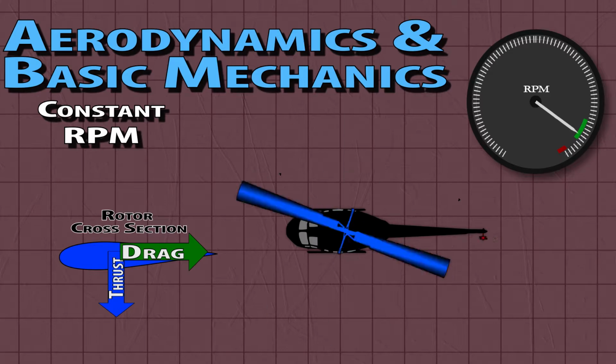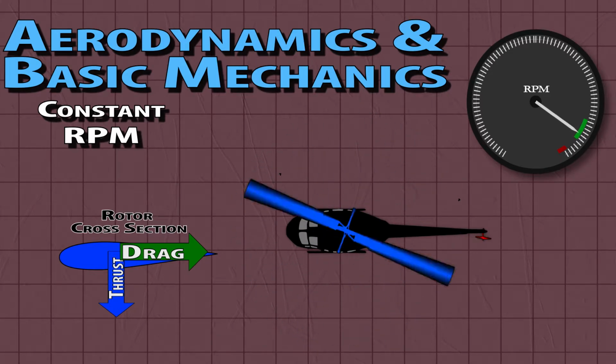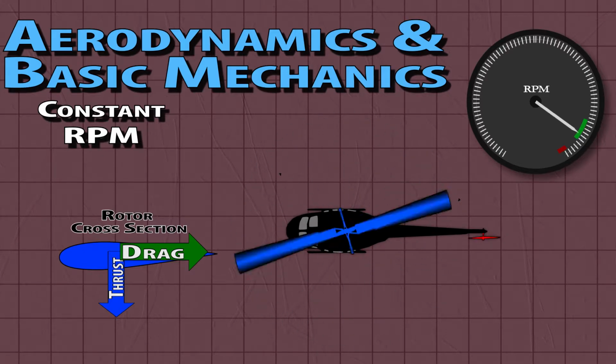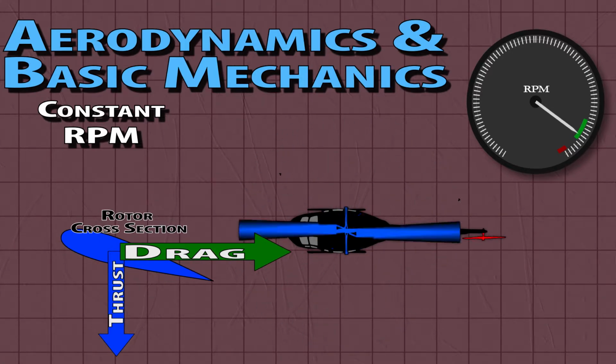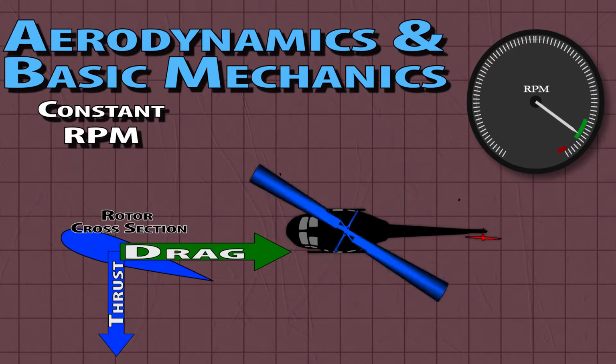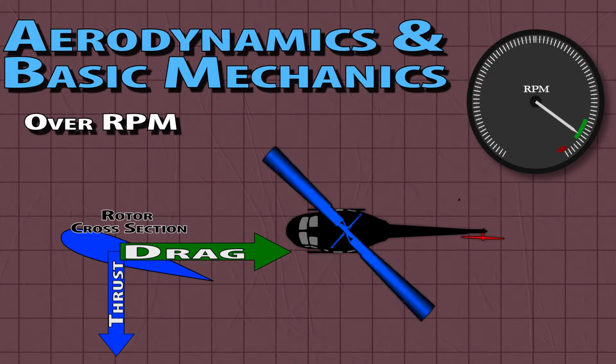In older designs, the throttle was managed by the pilot, and good modern pilots know how to fly with a manual throttle. However, newer helicopters have a governor, which will automatically maintain a set rotor RPM by adjusting the throttle. You can also damage the drivetrain or rotor system by letting the rotor spin too quickly. This is called over RPM. In powered flight, this can be fairly rare as your governor will reduce the throttle.